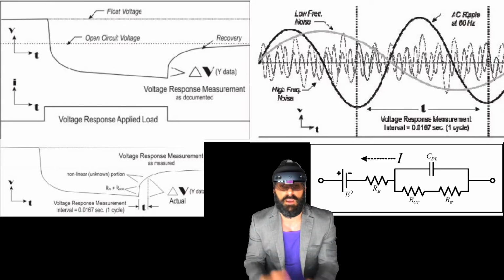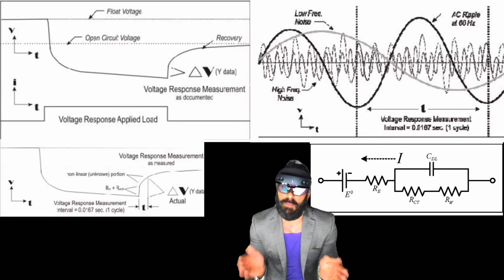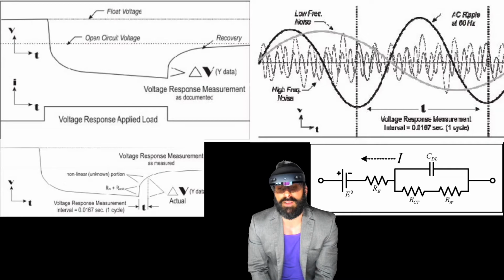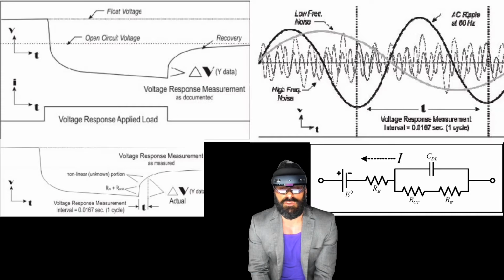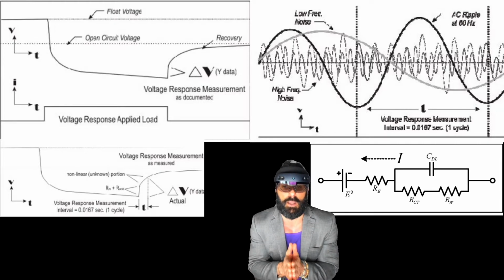and that's going to provide a resistance value based on Ohm's law. Now, these values are very accurate, they're repeatable, they're not impacted by noise, and the resolution is generally in the micro-ohm or milliohm range versus many of the other methods. Now, if you look at the Randles model equivalent circuit for batteries, you see resistive elements, R1 and R2, and the DC system is going to ignore completely the capacitive reactance of the battery. That capacitance, about 1.5 farads per 100 amp hours, is a very important component of the battery, and this is where AC conductance and impedance methodologies are drastically impacted.